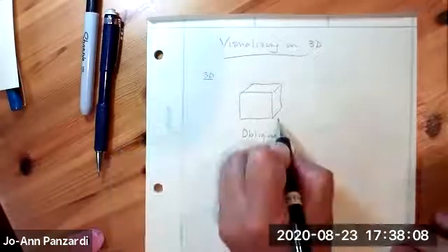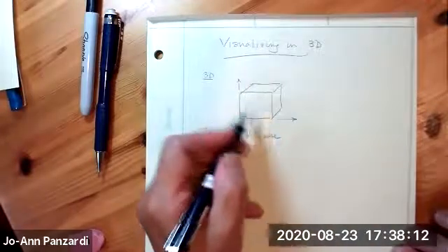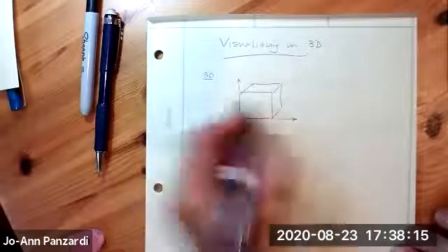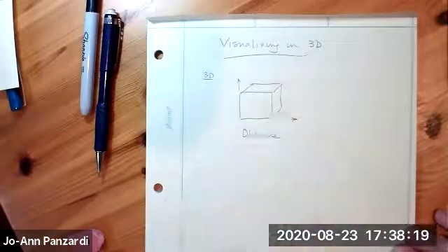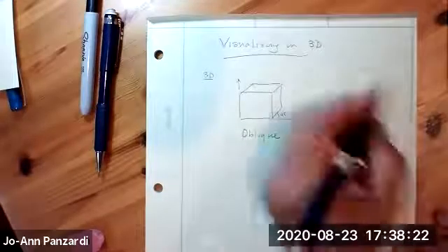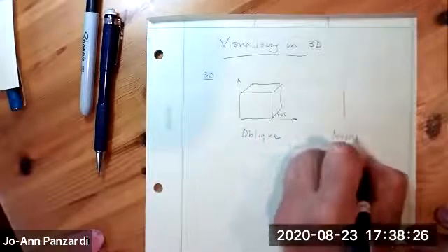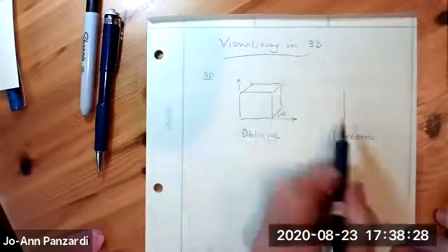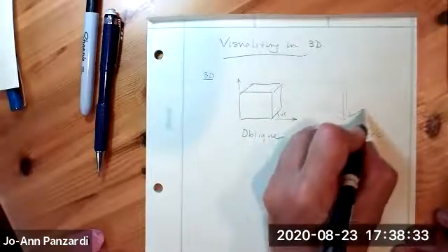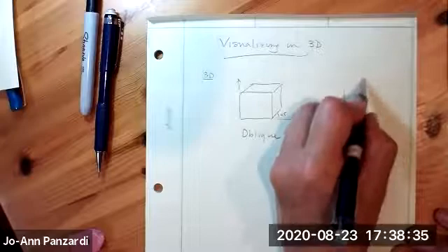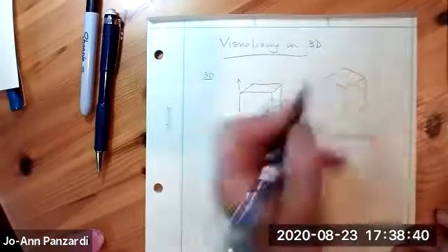where your axes is here and here, and the front plane is perpendicular to your line of sight, and then you draw the depth off at 45 degrees. The other way is to use what is called an isometric, where first you start this line, you're going up 30 degrees, going up 30 degrees, and then you are seeing your object all sides on true.